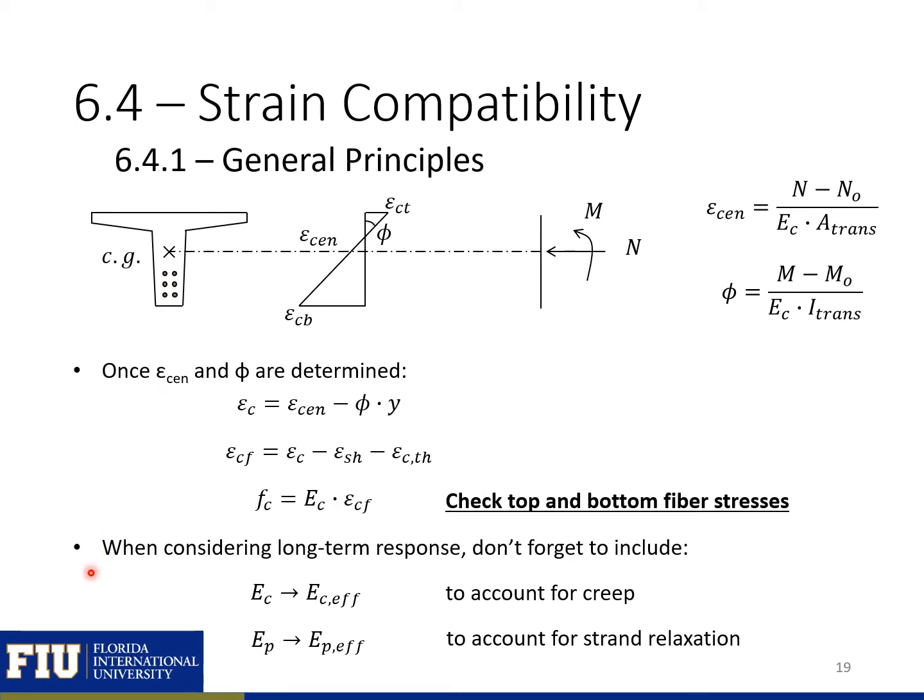Note that we can take into account creep and shrinkage and strand relaxation just by using our effective modulus for our concrete and effective modulus for our pre-stressing, and by including the shrinkage strain right here in this equation.